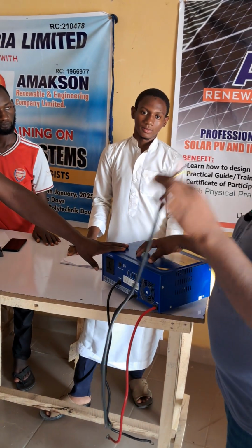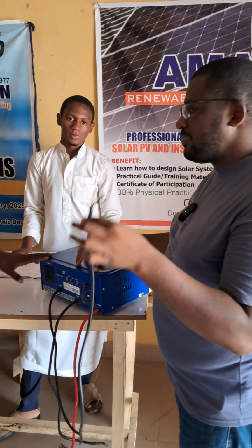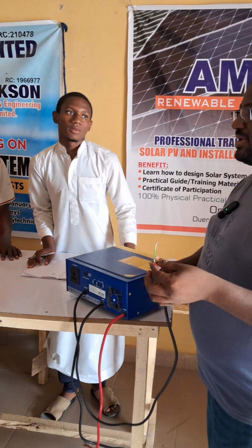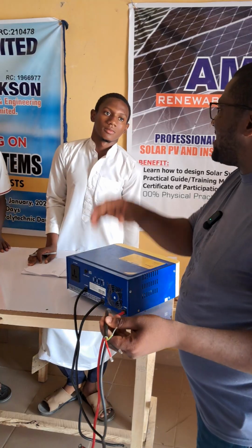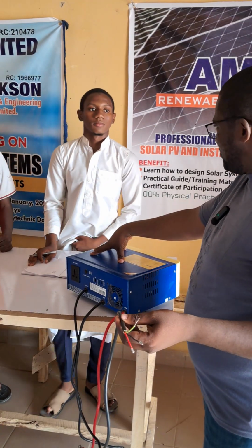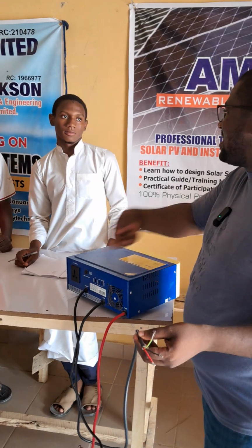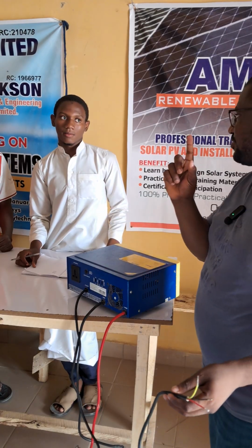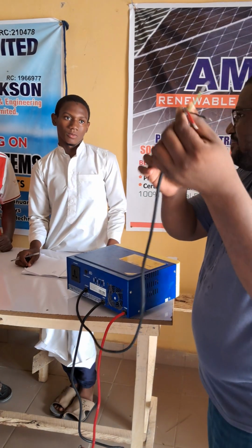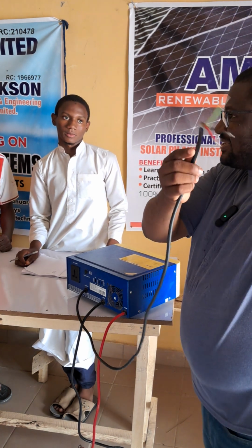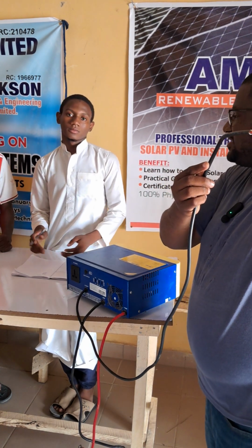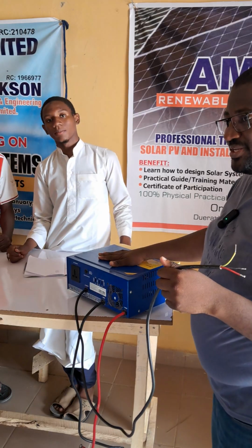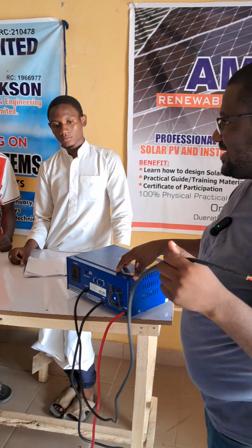If you want to power your inverter, you want to get your AC input, you don't just tap it from the socket outlet. Why? Because possibly your socket outlet is getting power directly from the inverter output. Do you understand? If you do that, what do you think will happen? There will be a feedback. A voltage from the inverter is also charging the inverter itself, which is dangerous. So you have to tap it from the DB, the distribution board, directly. It receives power from the national grid, from the pole, through the cutout, then you pass it here with control. Exactly. Do you understand?